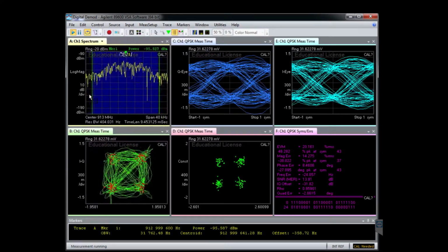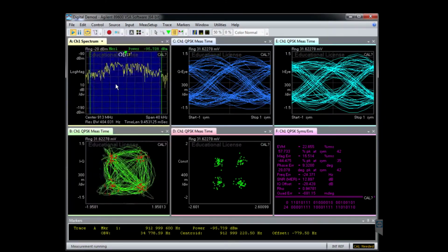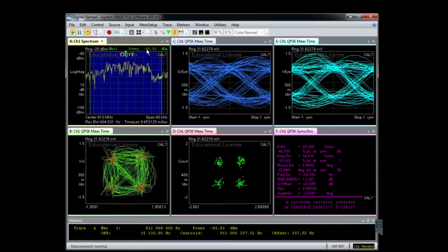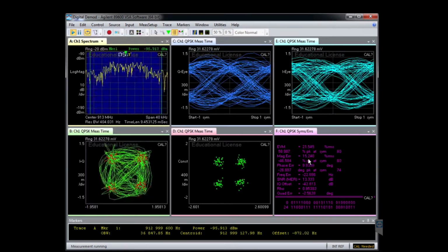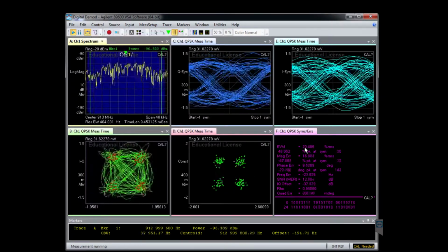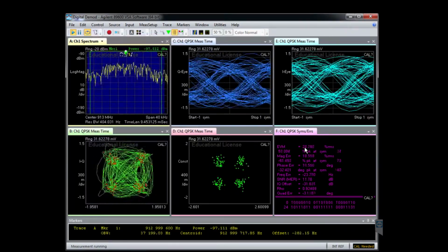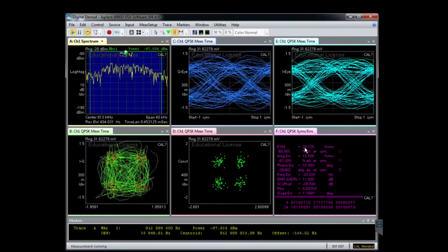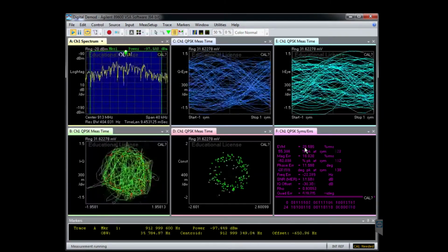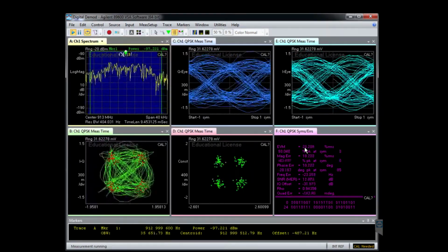You can adjust the marker accordingly. Yeah, something like that. So we can see the power that we are receiving is shown here, around minus 95 dBm, and the RMS EVM is around 23. We can take a note of these values. And the SNR is around 11 dB.